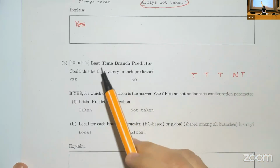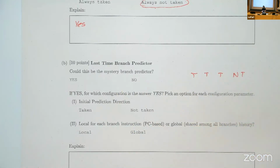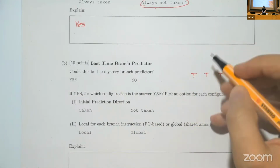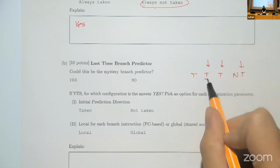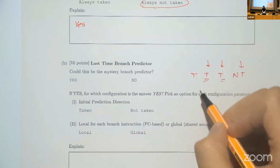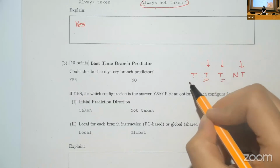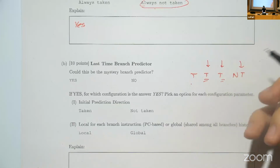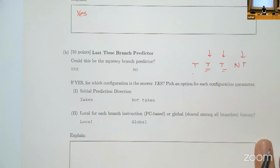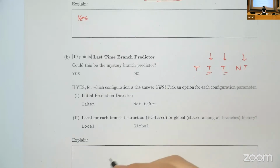You can see that if we predicted the outcome of the last branch each time, we would be able to guess at least 2 of them correctly, regardless of what we predicted this time. And you could also guess this one correctly if you started with taken. So we wouldn't be able to get 1 correct prediction and 3 mispredictions. So the answer for this is no.